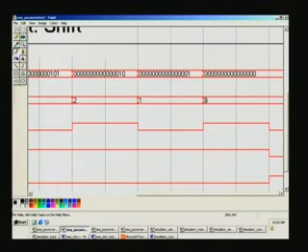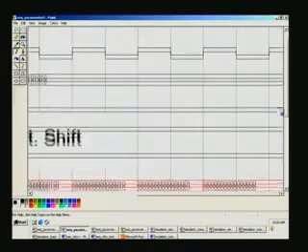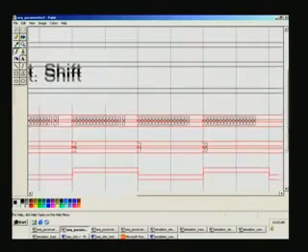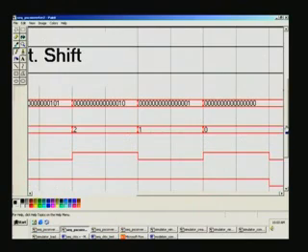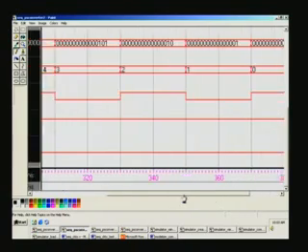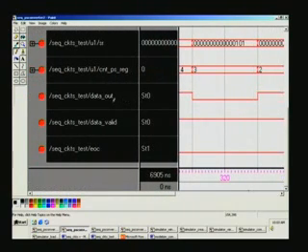And now you can see after this is over, and all these transactions are taking place at the positive edge of the clock. You can just see here. Every time it happens, positive edge here, positive edge here. You can see this. And finally an end of conversion is asserted here. So this is the last for the data, therefore data valid goes low. So the last two are data out here and corresponding data valid, end of conversion. So this is for the right shift.